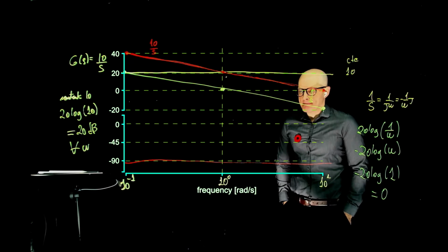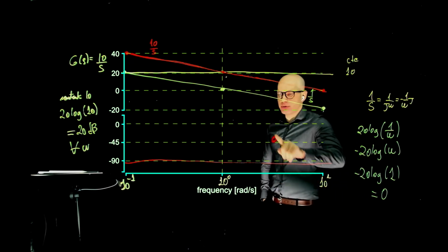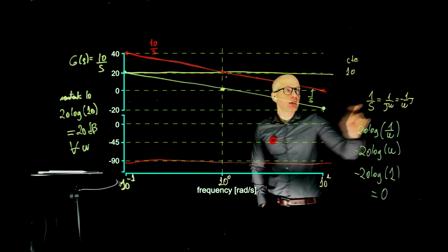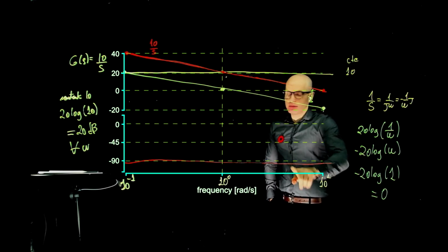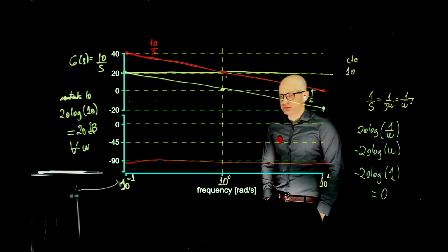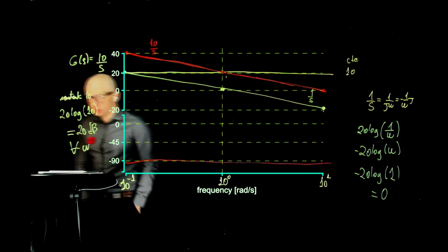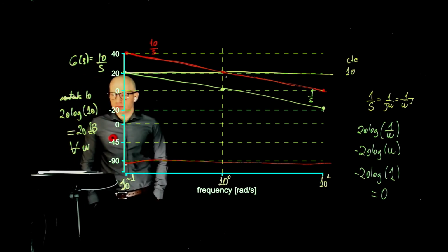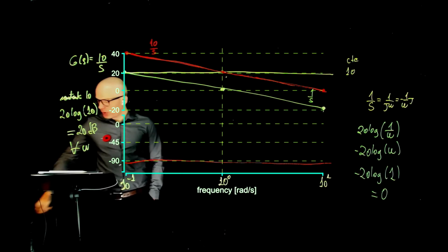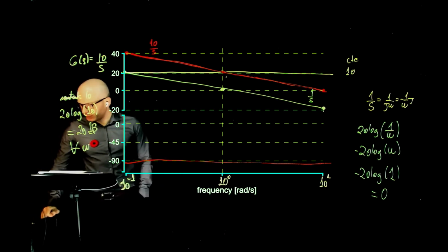Sorry, for the phase angle, you said that you added them? Yes, I added 0 from the constant gain and negative 90 for the pole at the origin. Perfect, thank you. Professor, I'm still a little bit confused about the phase because in previous slides, it's the n multiplied by the 90 degrees. Yes, so n in this case is 1. Oh, yes, it is 1. I'm sorry. My bad. Got it. Thank you.